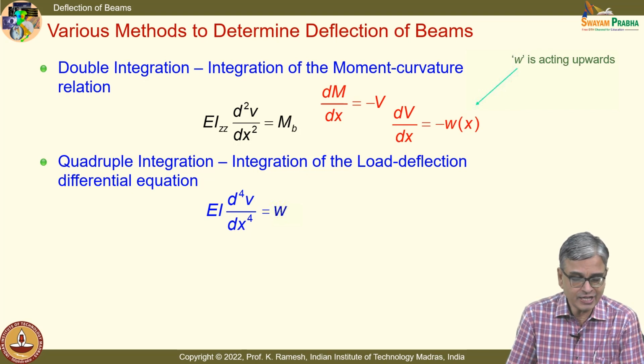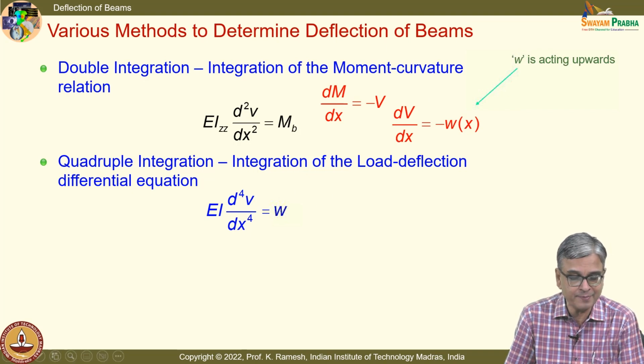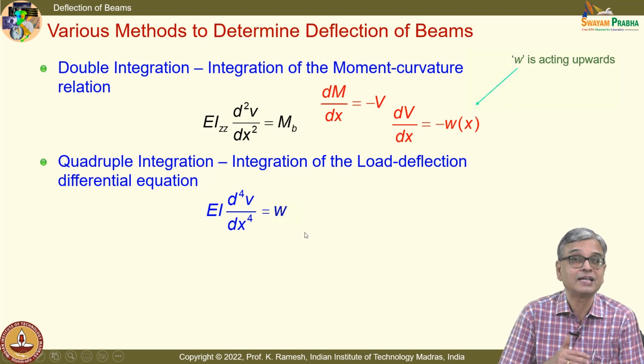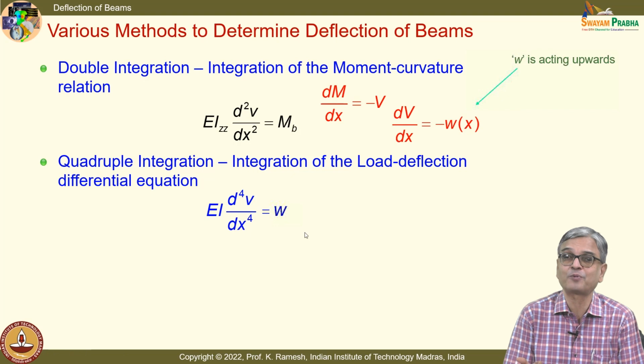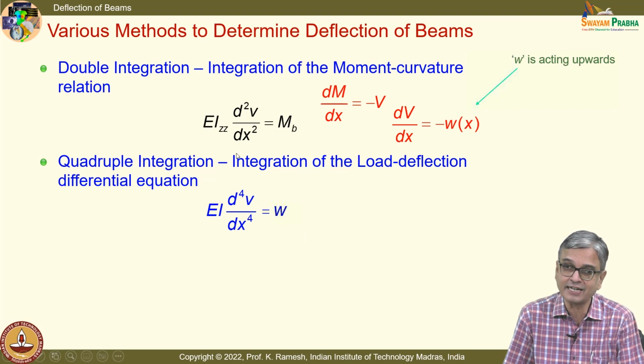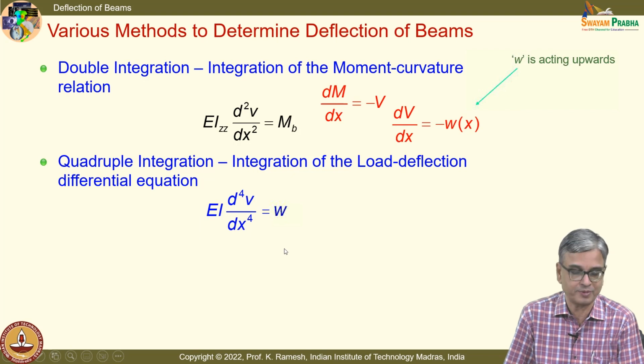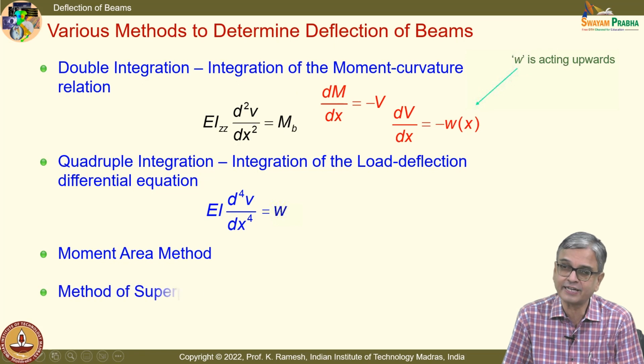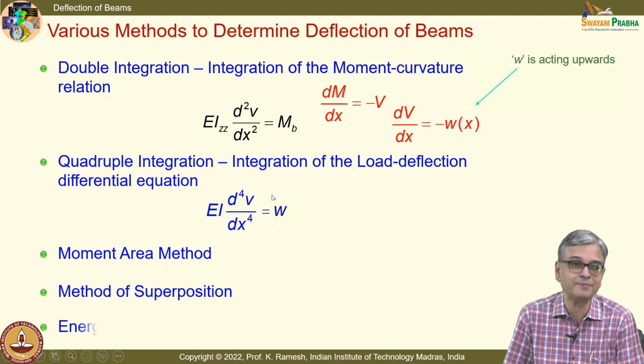On the other hand, if the load applied on the beam can be expressed as a continuous function of x, this is applicable even for statically indeterminate problems. So, this is primarily applicable for statically determinate problems. This is applicable for both statically determinate and indeterminate problems. And when you do this integration, you have done the integration mathematically.